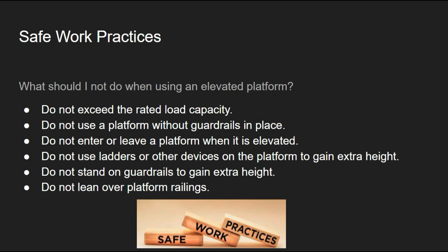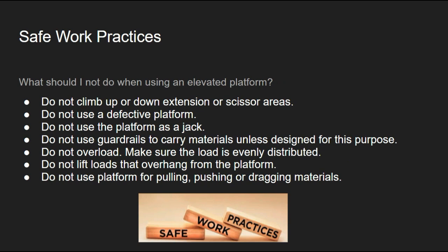Do not exceed the rated load capacity. Do not use a platform without guardrails in place. Do not enter or leave a platform when it is elevated. Do not use ladders or other devices on the platform to gain extra height. Do not stand on guardrails to gain extra height. Do not lean over platform railings. Do not climb up or down extension or scissor areas. Do not use a defective platform. Do not use the platform as a jack.